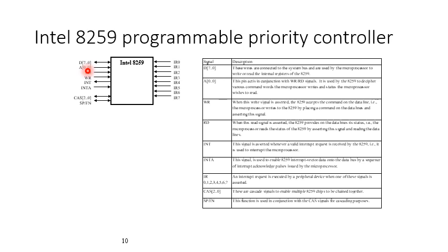We do not have any full address because we use the priority controller for the interrupt servicing routine, so we are just putting data on the data bus. Then we have a separate pin for the read signal, RD, and WR for the write signal.